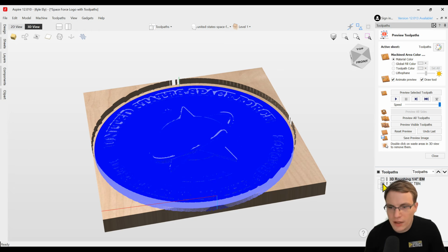Now let's go to our next toolpath, which is the 3D Finish toolpath. This is going to be with a smaller 16th-inch tapered ball nose. So this smaller bit, anytime you're using that smaller bit, you want to make sure you don't cut really deep in any areas in one full depth pass. And if you're familiar with 3D Finish toolpaths, they always cut in one full depth pass. So any deep parts you're gonna have to be careful of. This is a very common thing that I see happen where people break bits or ruin a project because they were not paying attention to this.